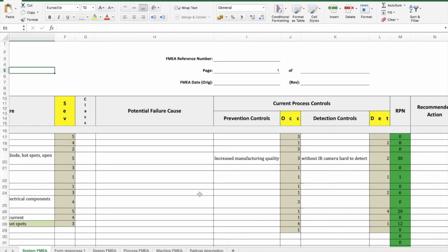Since the survey only got 6 responses, I cannot depend solely on the responses. I still have to refer to the literature review, and then from here we have 3 different ratings. We can get the RPN number by multiplying the severity rating, the occurrence rating, as well as the detection rating to get the RPN number.